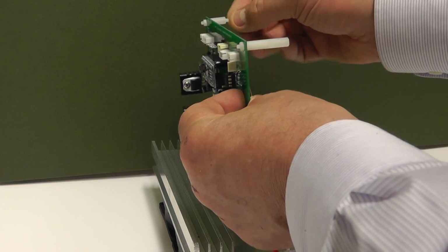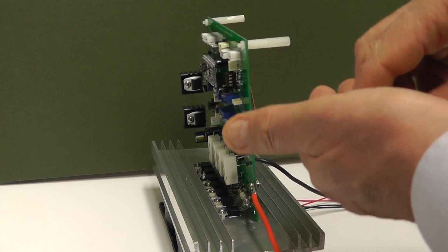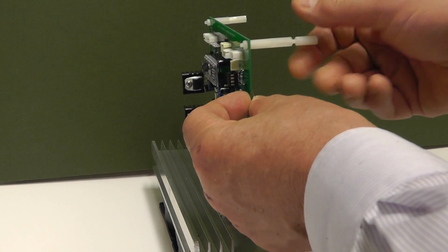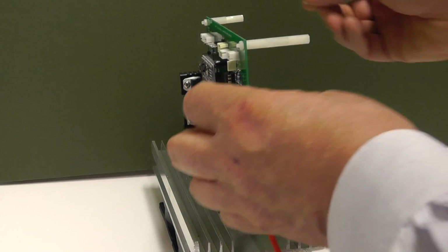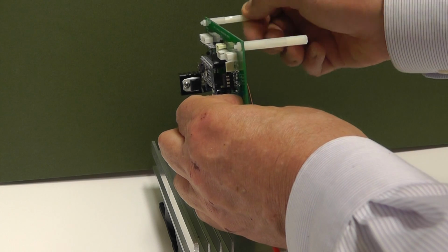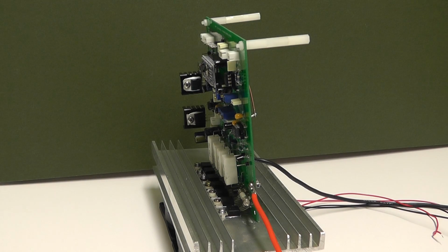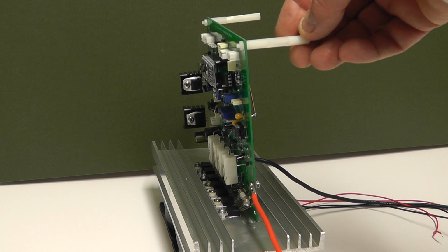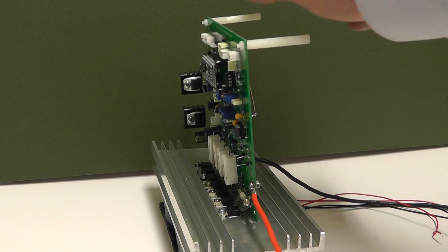But whatever method you have of fixing it into your project case, obviously it will depend on the type of heatsink that you choose at the end of the day and how high you have the PCB from the bottom of the project case. But in this case we're raising it to about 35mm. So there we are. There we have the standoffs now at the front of the PCB. That'll support the front of the printed circuit board when we mount the whole unit now into the project case.